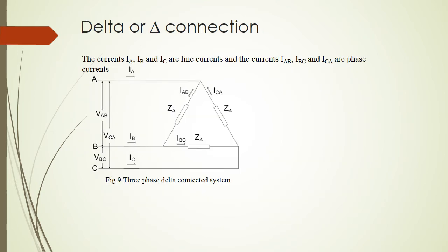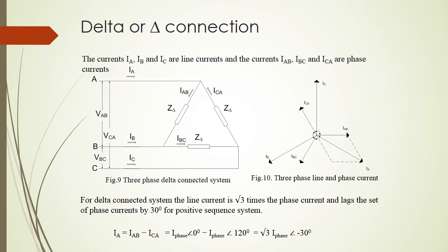We also have delta connection like this. In this case, we connect the load between the lines, and therefore the load is exposed to higher voltage, in this case 400 volt. As a result, the load current becomes smaller if we talk about the same power, and therefore the current in the line is 3 times higher than the load current.